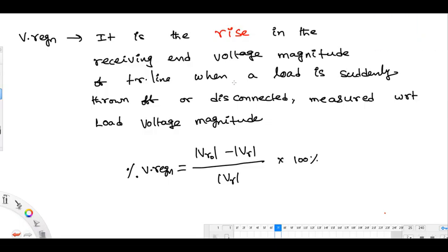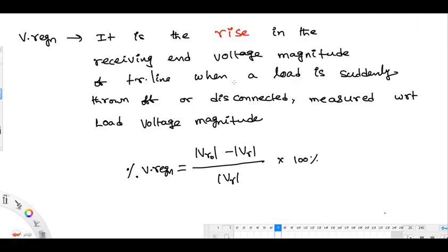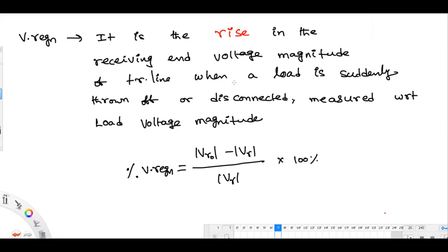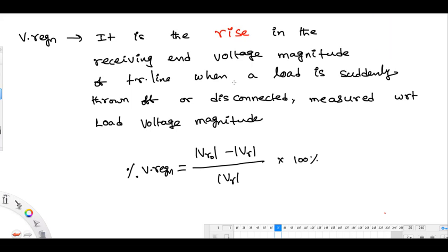In programming, how are we using it? For long transmission lines, they will go with EMTP, electromagnetic transient programming. It will give accurate results. So to get an accurate result, what I am suggesting is you go with the transient model. If you are not, that's your wish then.